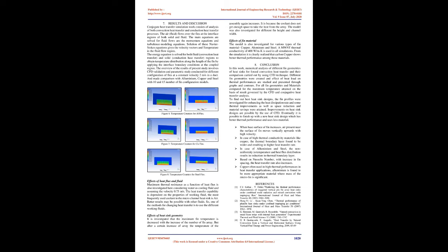Boundary conditions. The boundary conditions defined in the ANSYS Fluent processor serve as inputs for the model. The flow considered is laminar. The fluid used in this numerical analysis is air. A constant heat flux of 150 W/m² and a temperature of 373 K are assigned to the bottom wall surfaces. The inlet velocity is 2 m/s and is assumed uniform. A no-slip boundary condition is assigned to all the surfaces. The side and top walls of the MCHS are insulated. 0 gauge pressure is assigned at the outlet of the MCHS. In the ANSYS Fluent solver, the conservation equations are solved at discretized pseudo-time steps and the solutions are obtained based on the convergence of mass, momentum, and energy equations.